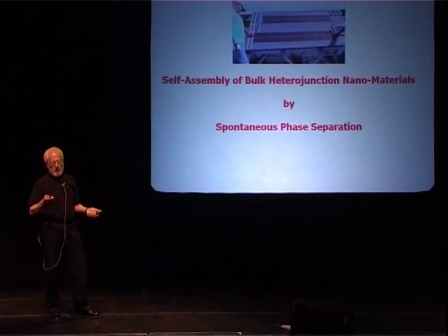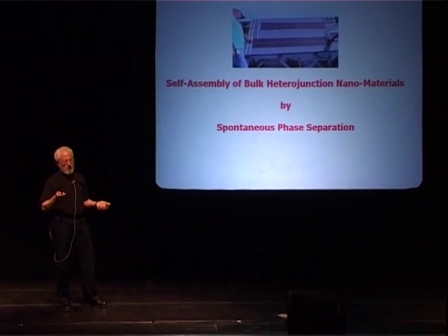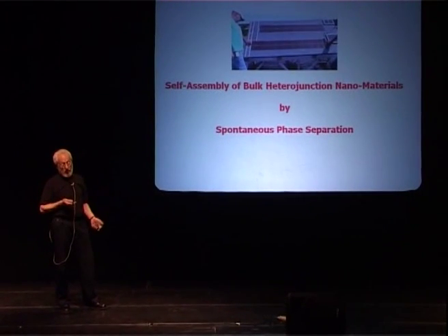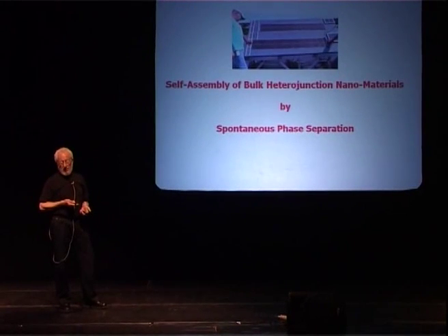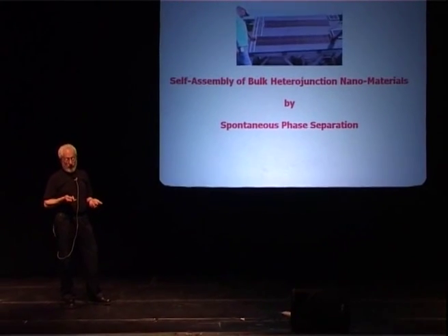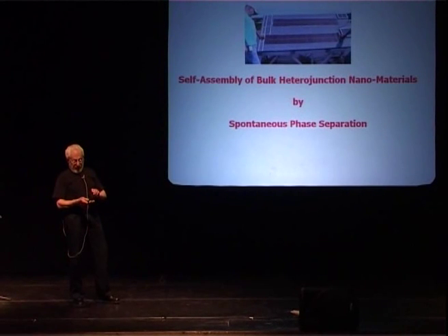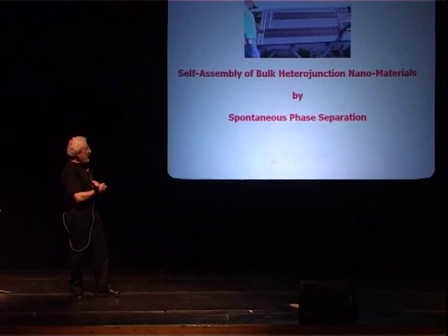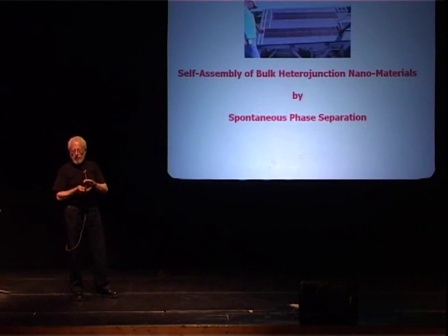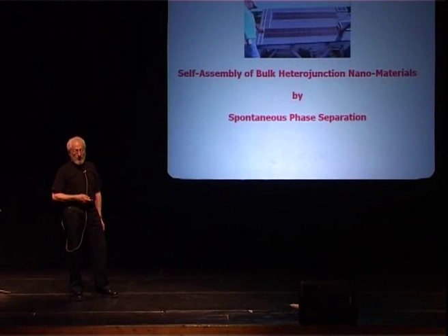The recombination length is less than 100 angstroms, maybe 100 angstroms. The length over which an exciton can diffuse before a recombination, less than 100 angstroms. This is not single crystal silicon. So even with a thin film, the thickness of this film is probably 100 to 200 angstroms. Even with a thin film, you can't get them out.